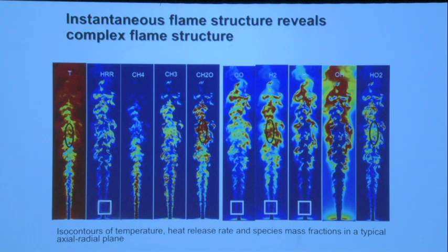So by contrast, when we move downstream in the jet, it seems like the first thing you see is that the preheat zone on either side of this jet is no longer at its original condition of 300 Kelvin, but it's preheated as you move downstream to higher temperatures, probably due to turbulent diffusion and possibly flame-flame interaction across the two sides of the jet. And so the preheat zone that is your upstream reactants is now at a different temperature.